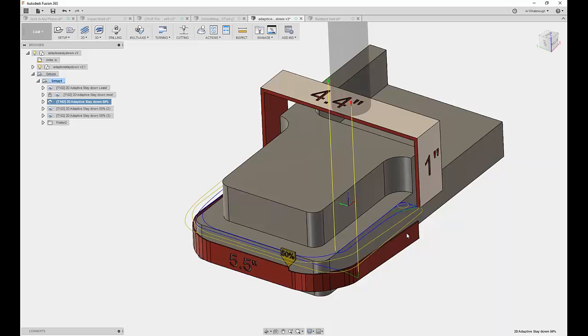How does it know that the rapid stay down is going to be 5.5 inches in this case without calculating that beforehand? It doesn't. So that's the point. It calculates the rapid first. The rapid is one line up, one line over, and one line down. It knows how long that is, and the percentage tells it this is how hard you can look for a solution. So it's searching its way through the stock, trying to find its way home. And once it's walked 5 inches, it gives up. It doesn't know if it's going to take 12 inches because it says you're done calculating. Stop trying. Gotcha. That makes a lot of sense now.